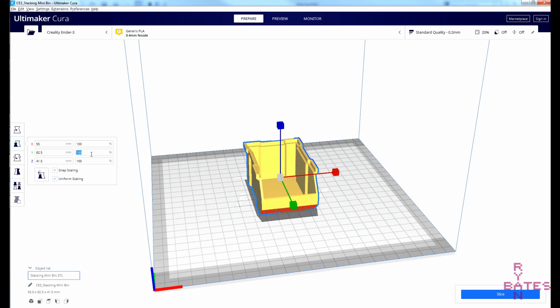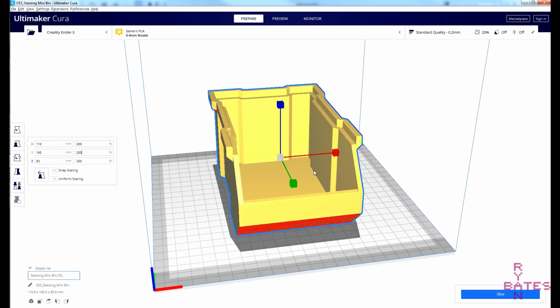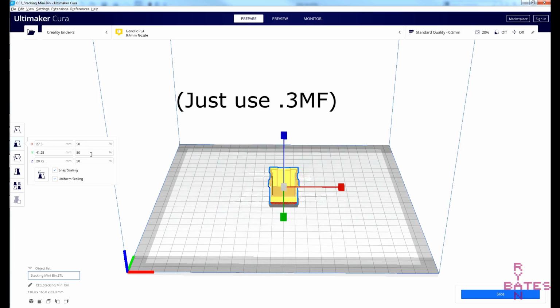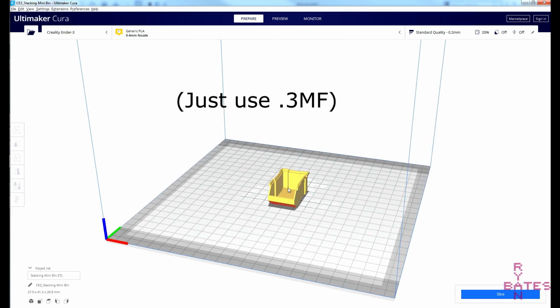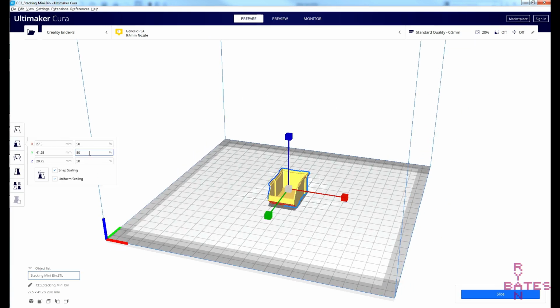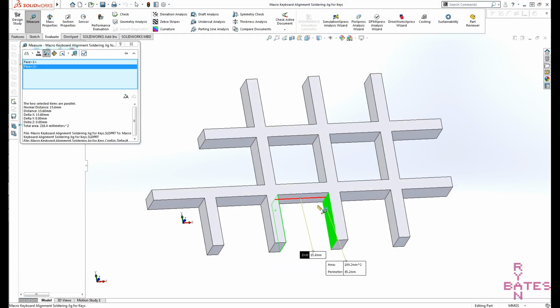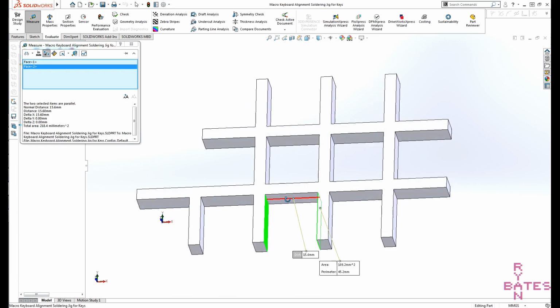The STL format has been around for over 30 years, hence its apparent high popularity and wide adoption. .3mf is relatively new compared to STL, but vastly superior to STL. 3mf delivers complete model information into a single archive. Regardless of the file format you pick, note that most fused deposition model-based prints will shrink.